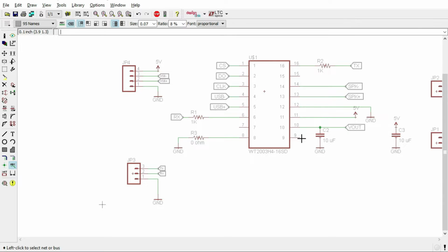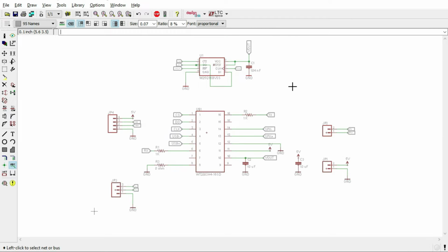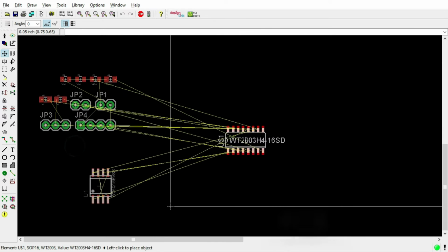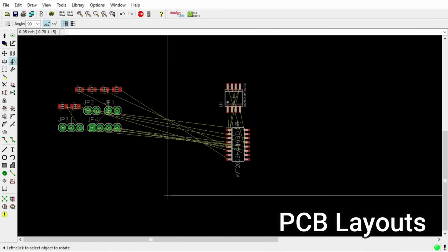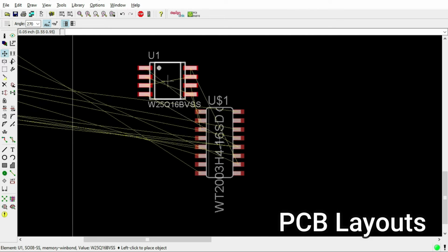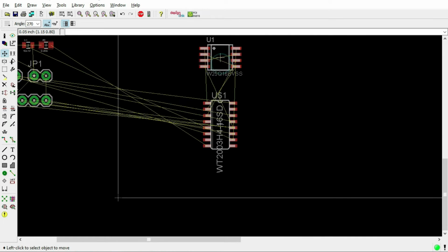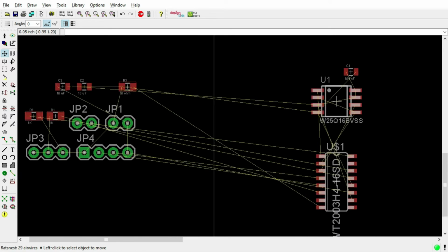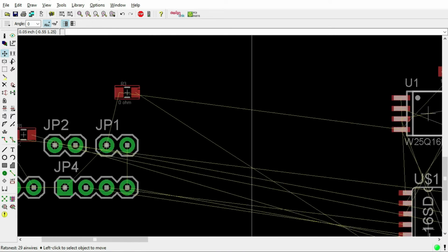Okay, we have finished working on the circuit schematic. Hopefully it can be seen clearly. Next we will lay out the PCB. The PCB design that we make will use single-layer FR4 PCB material. We will make this PCB as efficient as possible. Even though it's only one layer, we will try not to use jumpers for the paths between components.